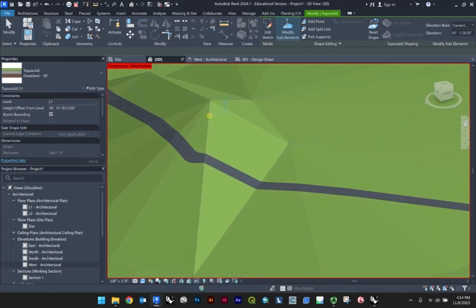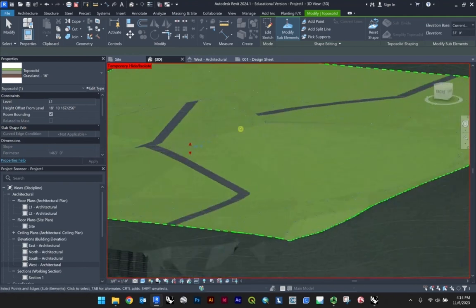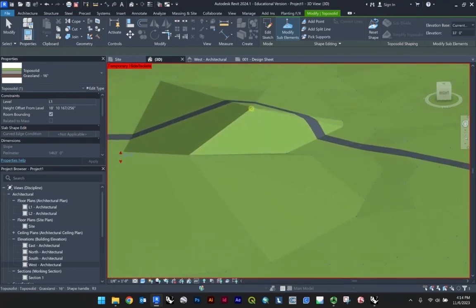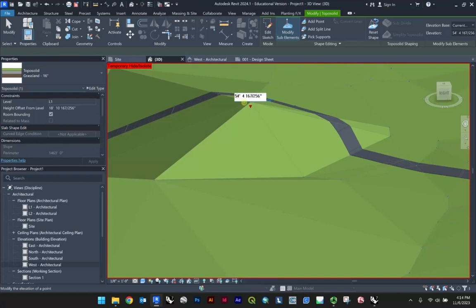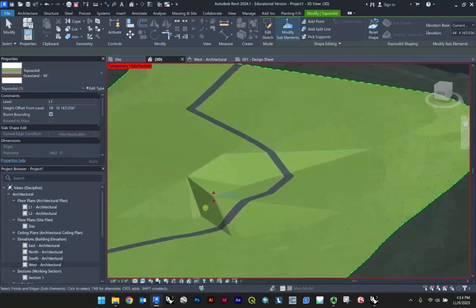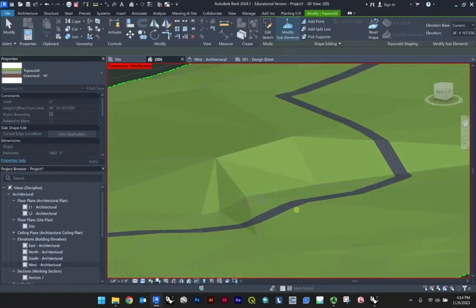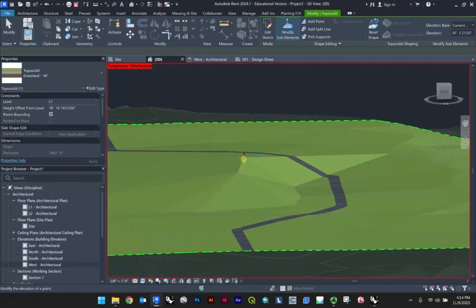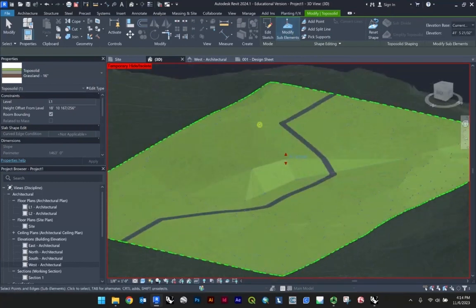And so you can start to move this up and down. And these are all going to be relative heights. So you can actually click and say like 33, hit enter, and see it'll kind of go up and down relative to whatever value. So if I wanted it to go down 10 feet from this value, I could just change that out to a 4 and it drops down for me. So pretty nice feature, kind of a real-time way to regrade your site and instant feedback in terms of the pathway you've selected, for instance. So hopefully you find that helpful.